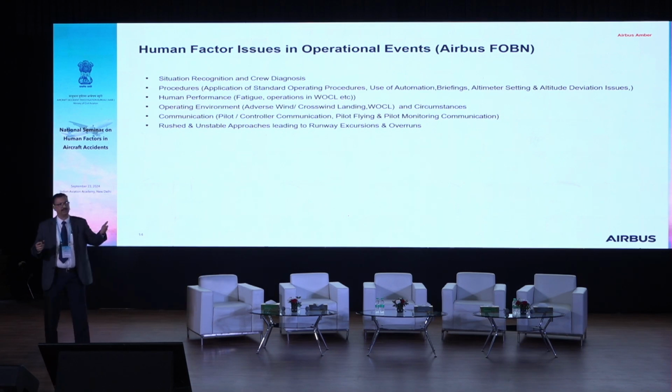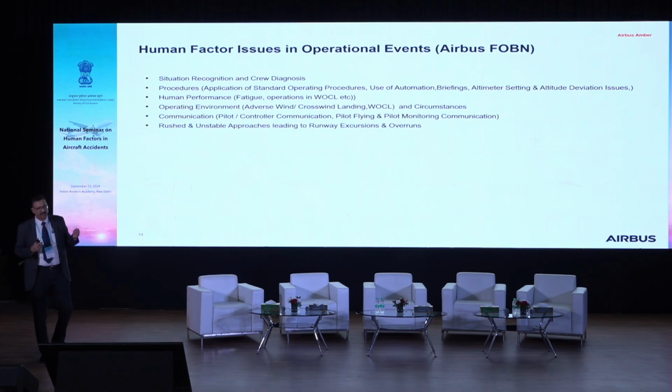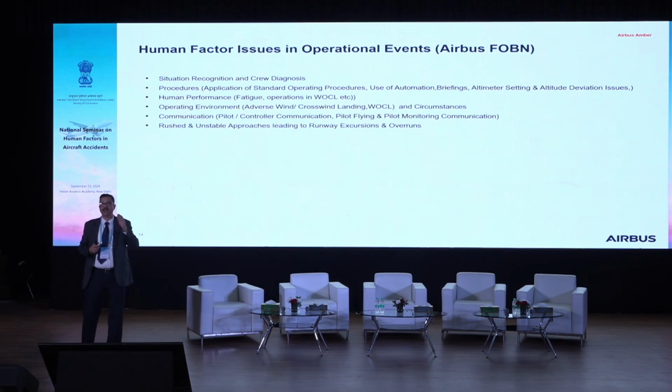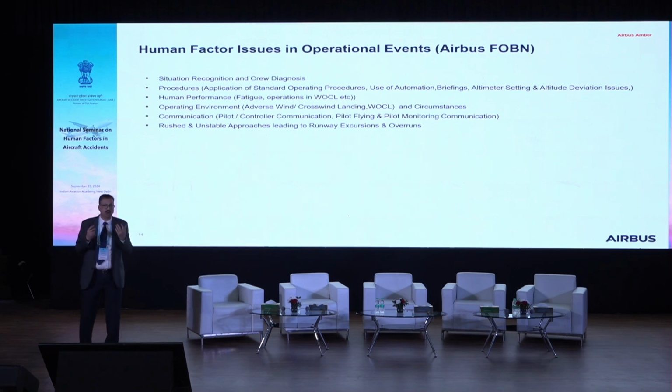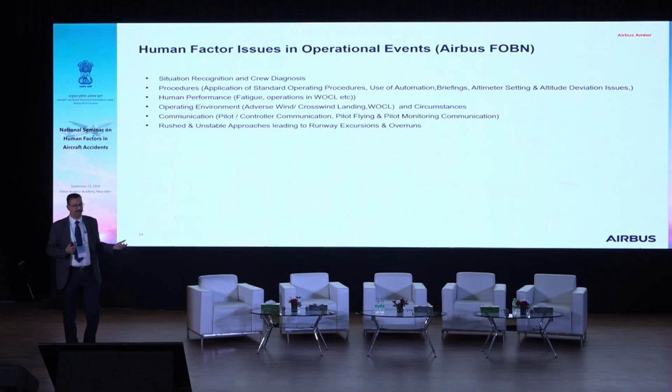Operating environment, as I mentioned, 49 degrees heat. Coming into land, maybe in London Heathrow with crosswinds about 40 knots. All these things will affect, after flying for 8 to 10 hours. Communication was brought out earlier, but this is one element which we find is there in practically all the events which are taking place. Especially when the technology is improving, we find that the flight crew communication is getting affected, and we find that the communication levels are on the lower side. That's why our standard operating procedures very clearly define what is an active monitoring process, what the pilot monitoring needs to call out, how it needs to get acknowledged by the pilot flying.